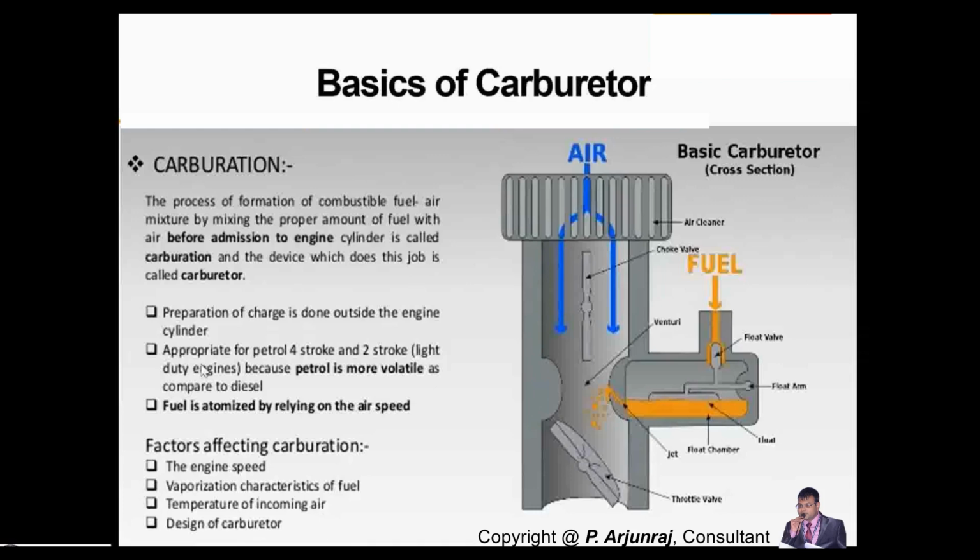The preparation of the charge is done outside the engine cylinder. Here the charge indicates the air and fuel mixture, which is prepared outside the engine cylinder. The engine cylinder here is basically the combustion chamber. This is appropriate for four-stroke and two-stroke engines, especially for light-duty vehicles, because petrol is more volatile as compared to diesel.